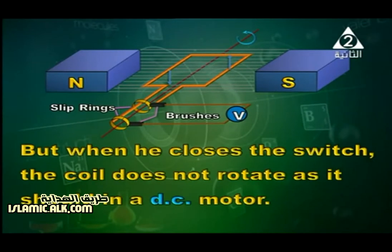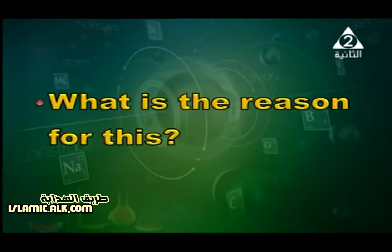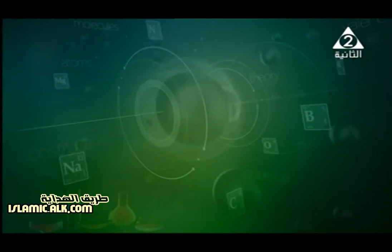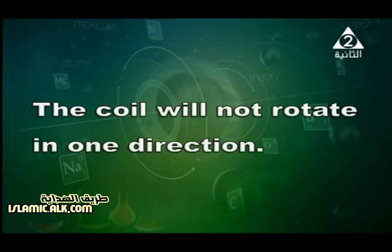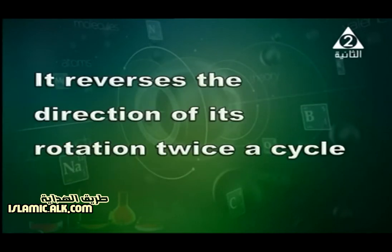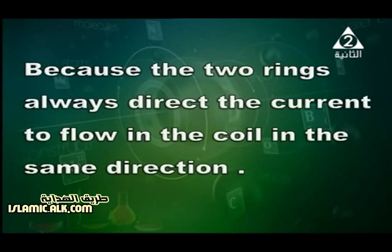But when he closes the switch, the coil does not rotate as it should in a DC motor. What is the reason for this? What is the problem here? As a matter of fact, we've got two rings, so the coil will not rotate in one direction. It reverses the direction of its rotation twice a cycle, because the two rings always direct the current to flow in the coil in the same direction.